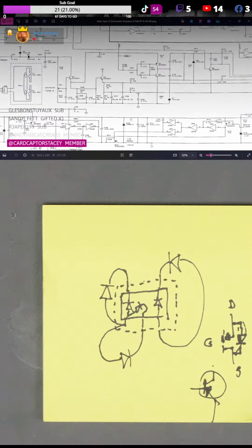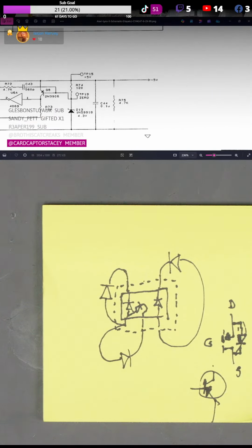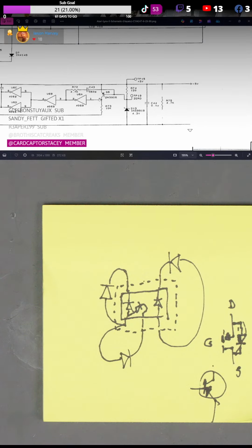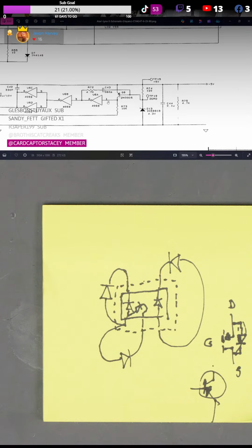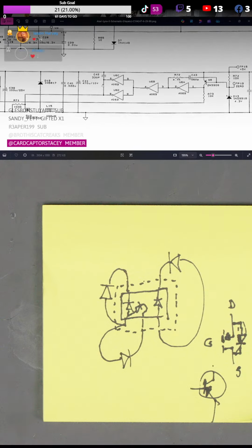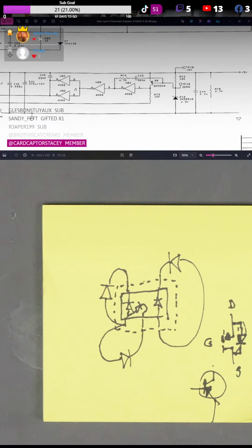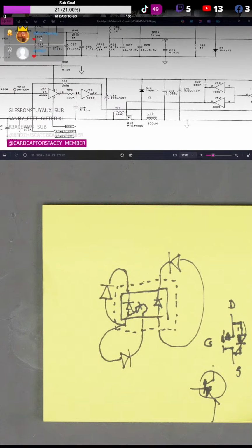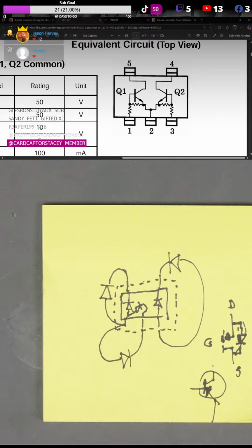So pull this up. So we have on this circuit, we've got a Zener diode here, basically. But this just goes through, again, a basic transistor. So that will be a PNP transistor there. Yeah, and this isn't an op-amp. This is a hex inverter, basically. Yeah, so that doesn't give me any clues. But I don't think it's going to be an array, unless I'm staring at it and misinterpreting where the diodes are going.